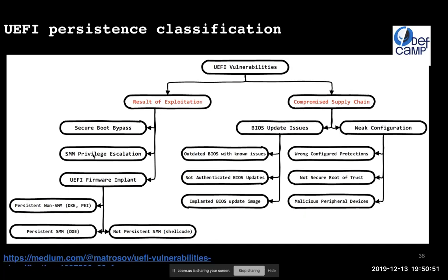Not all hardware vendors even have authentication for BIOS updates. And if we talk about firmware updates, there are multiple firmwares on your platform. In many cases I've seen, for example, the embedded controller just flashed directly to the chip and not authenticated at all. All of these vectors will be covered in the class, and we will talk about these details and examples and do some labs on many of them.